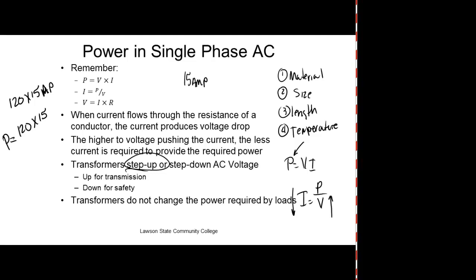You can handle 1800 watts of power. So as long as you flip on a light, and that light's a 100-watt light bulb, right? You understand? How many 100-watt light bulbs could you run? So it's 1800 watts of power that's available to pass through that breaker.